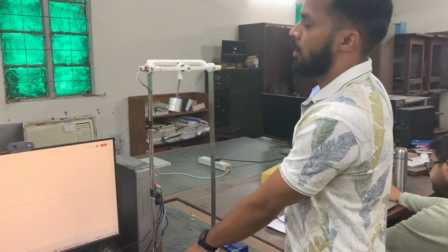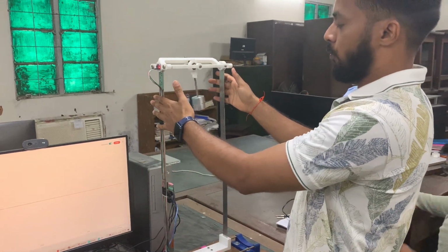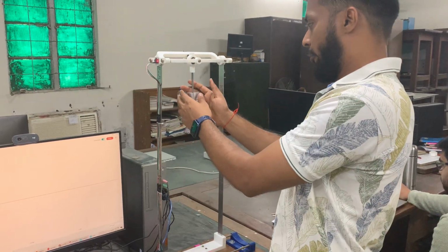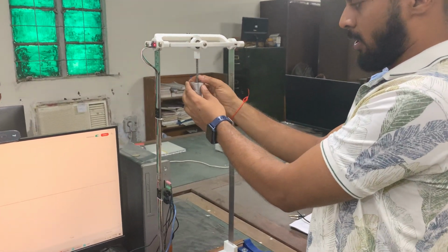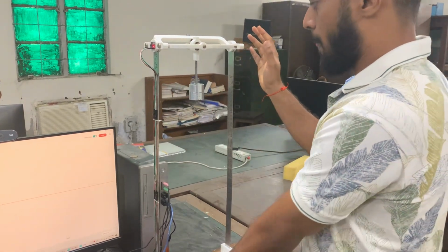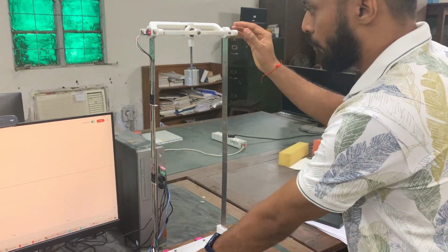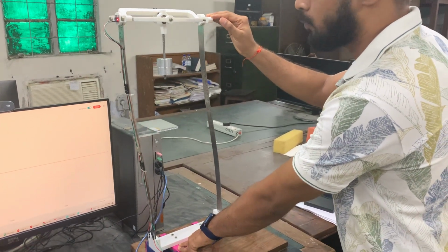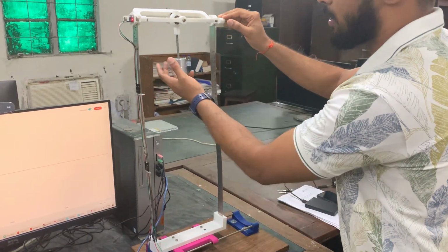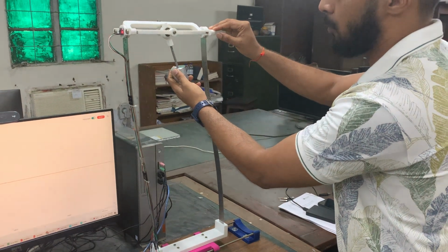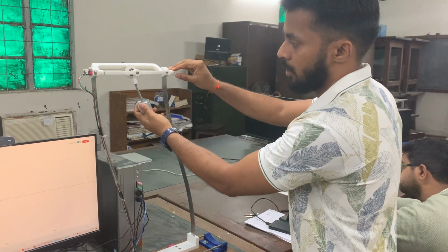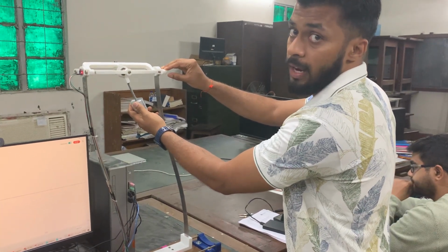So how it works is like, this is a model for the skyscrapers and this is the tuned mass damper, which has some mass and some length here. So we ensure how it actually works. Let me show you that. When we move the structure in this direction, when it gets moved by the vibration of the earthquake or any storm, then this mass has some inertia. It will remain at the same location, and this skyscraper will move in the opposite direction. So it opposes the motion. It acts as a restoring torque.